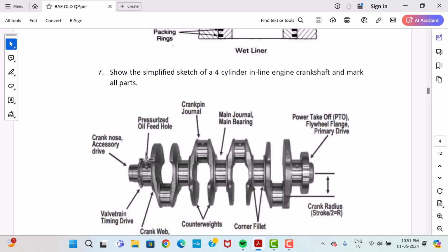In this portion, this is the position where the main bearing comes. You can see an oil hole here. This is a small hole through the shaft, and it is connected to this point, and this point. Again, you can see the holes here and here. At every point you can see the holes that provide the connection.